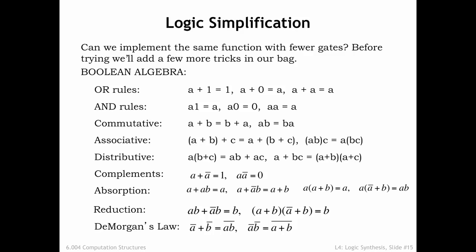The previous sections showed us how to build a circuit that computes a given sum of products expression. An interesting question to ask is if we can implement the same functionality using fewer or smaller gates. In other words, is there an equivalent Boolean expression that involves fewer operations? Boolean algebra has many identities that can be used to transform an expression into an equivalent and hopefully smaller expression. The reduction identity in particular offers a transformation that simplifies an expression involving 2 variables and 4 operations into a single variable and no operations. Let's see how we might use that identity to simplify a sum of products expression.